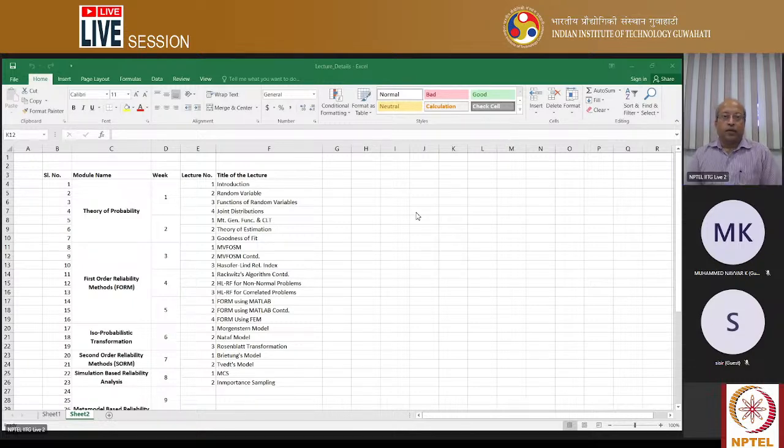Then it was followed by some corrections on the first order reliability method proposed by Breitung primarily. That deals with the correction based on the curvature at the design point. We have seen that if the curvature is really prominent, then its effect is also reflected on the overall probability of failure. And then finally, once we discuss all this gradient-based reliability model, obviously the question comes to your mind: how can we verify this result? Is there at all any way? And in fact, not only that,